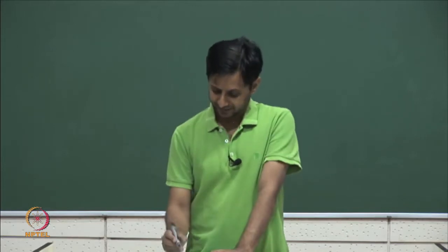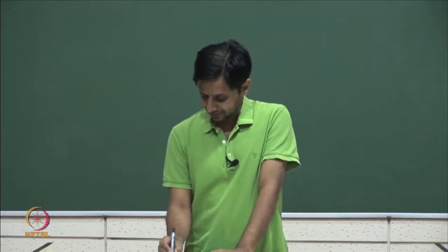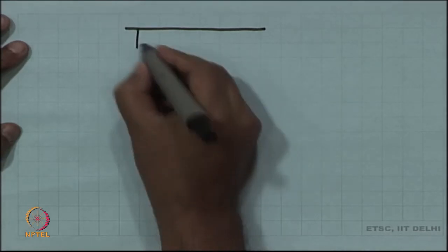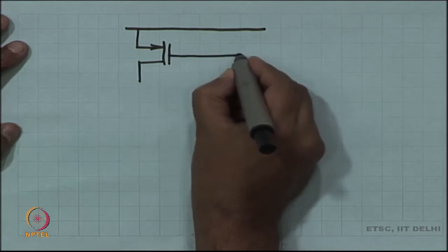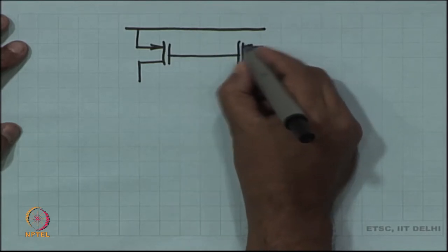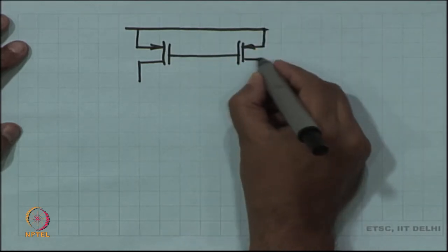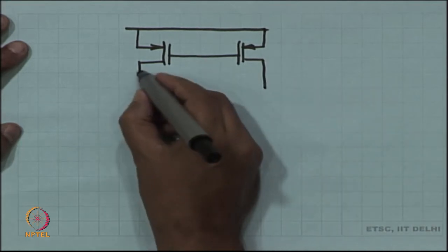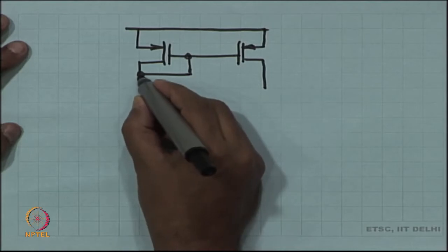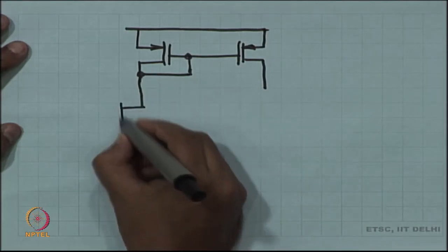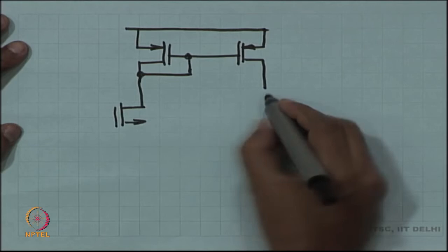Today we are going to talk about the self biased active load differential amplifier, differential input, single ended output. The circuit we were discussing in the last class was a setup where I had a differential amplifier, but the load was a current mirror as opposed to a regular active load PMOS on each output.